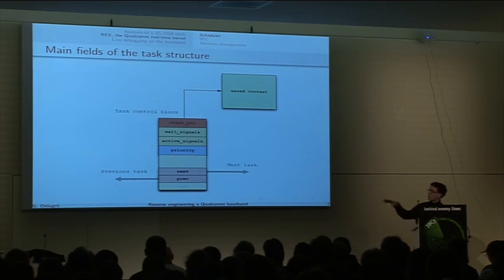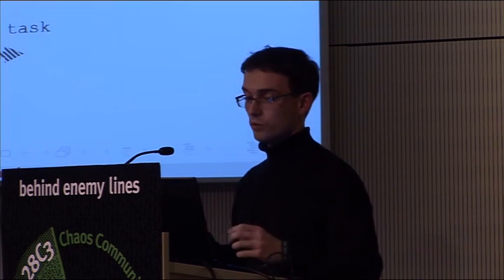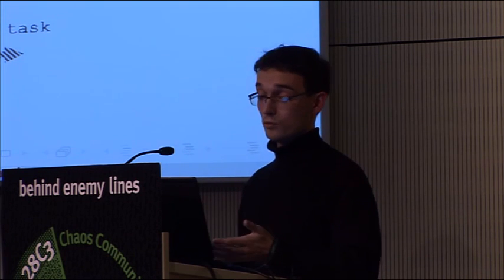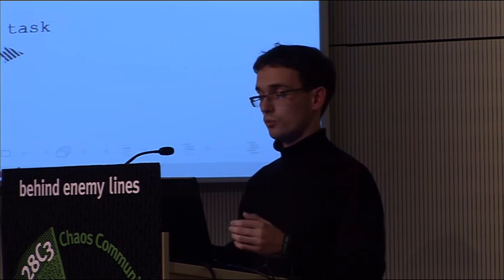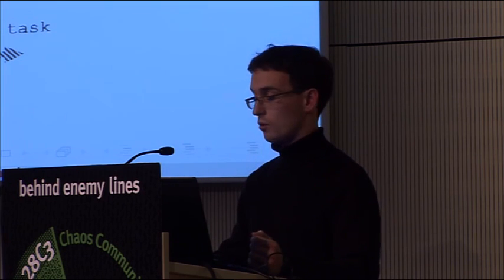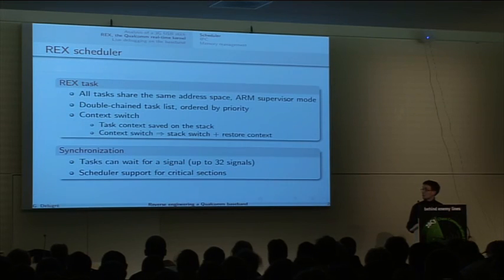There are a lot of fields; I'm just putting the main fields here. Each task has a set of signals which can be fired or cleared. A task can wait for some signals, and another task will send a signal for the task to resume. The tasks are also, of course, ordered by priority. As I said, the context switch is very easy. The scheduler also supports critical sections.